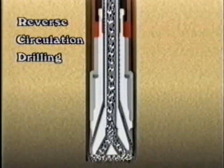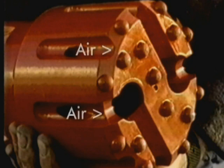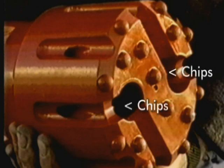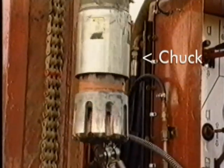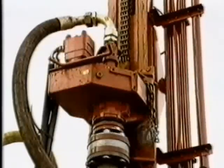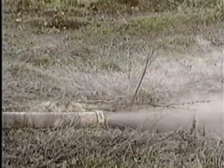This is achieved through the design of both the dual wall and the drill bit, which has special channels to enable air to travel through the bit. These channels enable flushing air to travel down through the bit. The chip samples are removed through the two large holes located on the bit's cutting face. The hammer has an oversized chuck which seals the hole behind the bit. A collection unit is normally used to gather cuttings. In this video, it's been removed to properly highlight the volume of cuttings produced and the air flushing media being used.